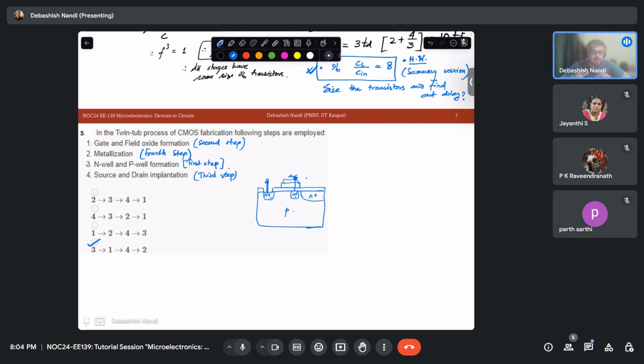Okay, so I have not gone into the details of fabrication. I think in lecture Professor Dasgupta has also touched upon it very briefly. So you understand that it is a bottom-up process, and multiple layers of masking. Photolithography is what? You apply a photoresist, cover some portion with a black mask, cut some window, apply UV light, that photoresist will get dissolved, then etch back the oxide.